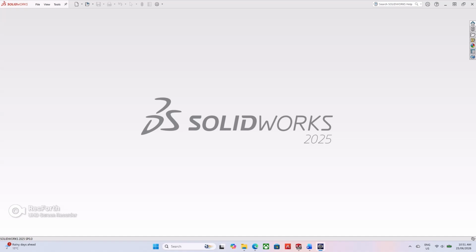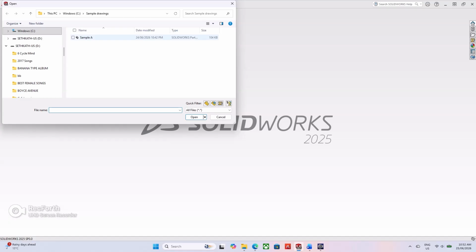In my previous video, I showed you how to create a 3D model from a sketch in SolidWorks. Today, I'll take the next step and show you how to create a detailed 2D engineering drawing from that 3D model. We'll cover the process of placing views, adding dimensions, and preparing a professional drawing that can be used for manufacturing or documentation. First, I will open the SolidWorks 3D part by going to File, Open.